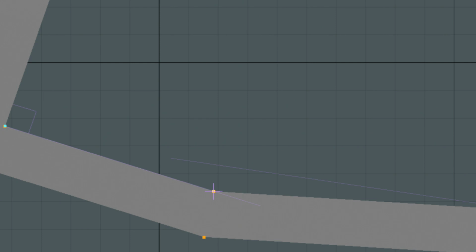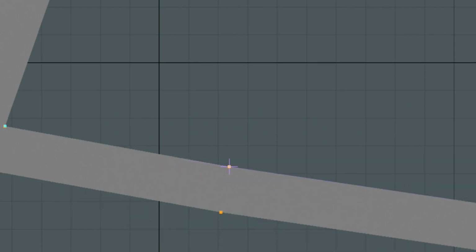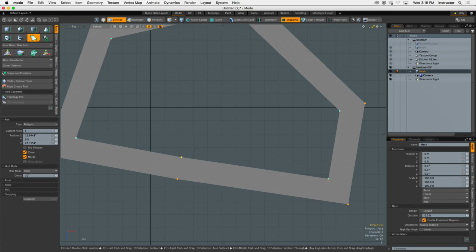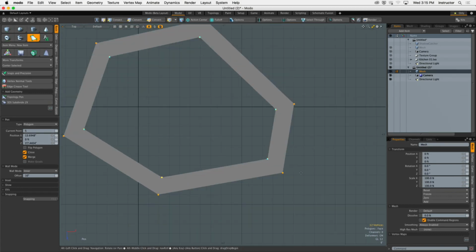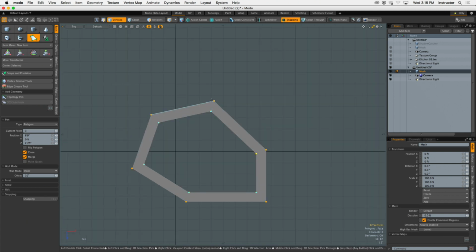We're also getting a preview. See that little line showing up? I just had it. See the little purple line showing up in the OpenGL viewport? That's telling me that if I was to put my vert there, it's going to be either a 90 degrees or a straight line to another vert. So we're getting some really good feedback here from the computer that's allowing me to very quickly make some 90-degree corners. Okay? Like there it is. Now I have a 90-degree corner in that edge.